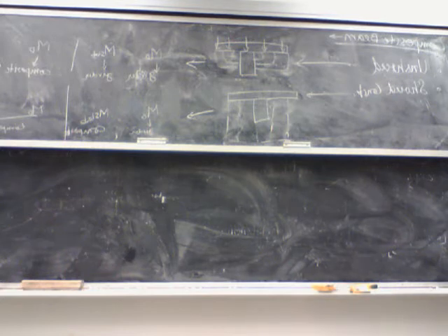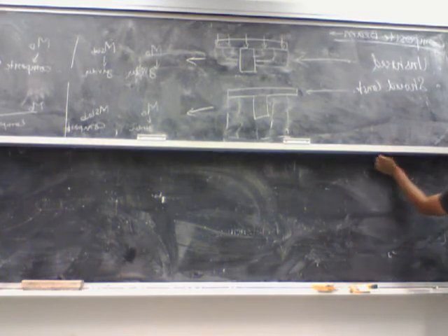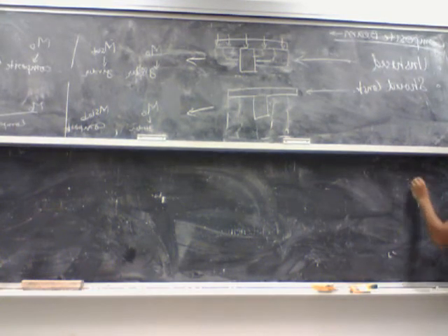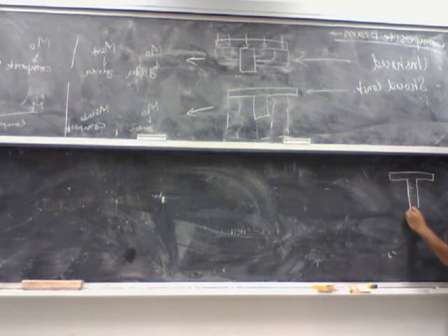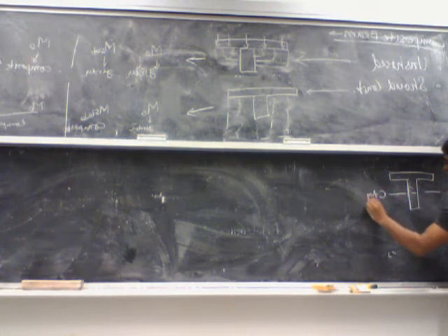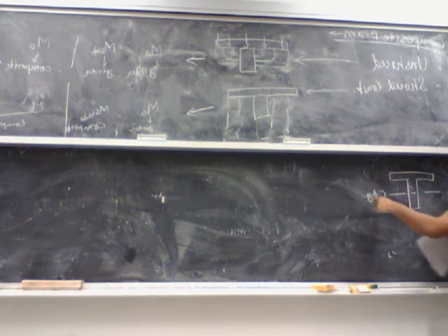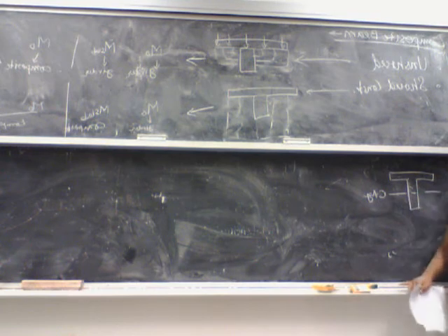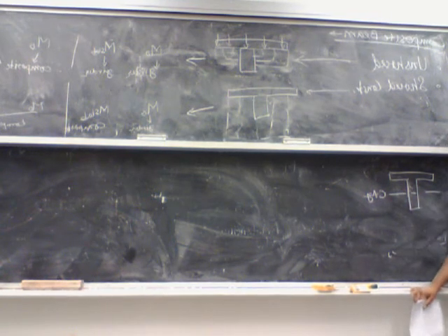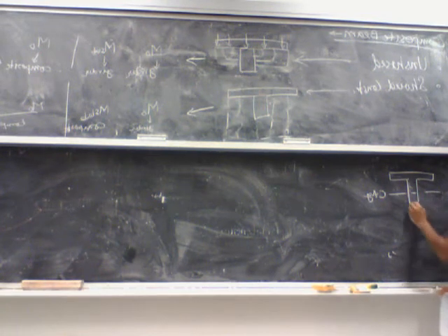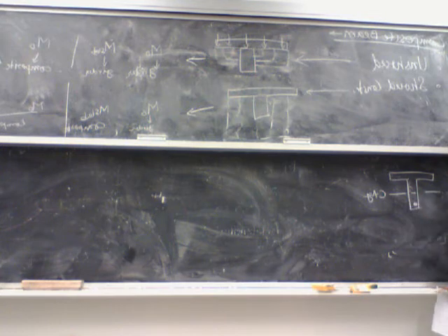Before I write the equations, let's say this is my girder, and this is my centroidal axis of the girder. Anything with a subscript G means it's only the girder, and anything that ends with a subscript C means it's a property of the composite section. Let's say this is the location of the centroid of the pre-stressing strand.